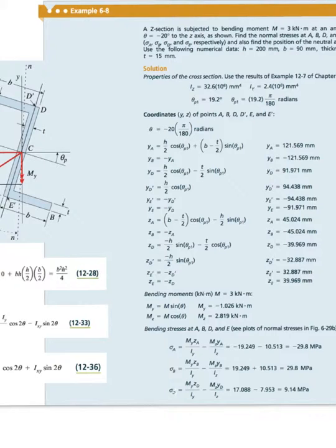In normal circumstances, where the z-section is not tilted, as we can see in our example here, Iz and Iy are straightforward and simple to calculate using the standard equations of moments of inertia and the parallel axis theorem for areas that are offset from the neutral axis. To read more about the parallel axis theorem, please refer to chapter 12.5.